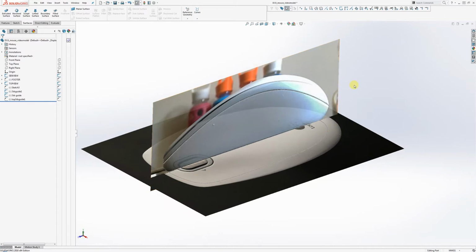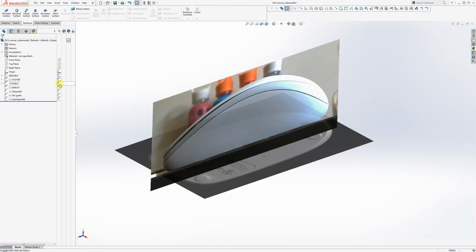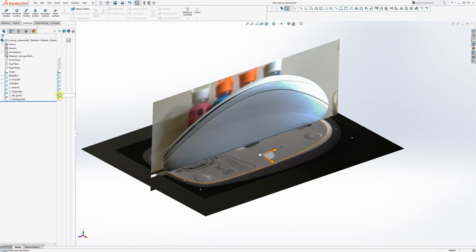First thing you notice when you look at this is that I've got these images imported into SolidWorks. And I want to show you over here in my design tree, I've named each of these so that they're easier to find, because I'm going to be toggling them on and off throughout the entire process. You can see here in capitals, I've named them. And you can also see that I've got this little arrow at the top of my design tree, which displays these toggle buttons for the visibility of the images, so I can turn them on and off one by one. I can turn off all the different parts of the model right here with these buttons. And so this just makes it easy for me to show what I need to show depending on what step I'm at.